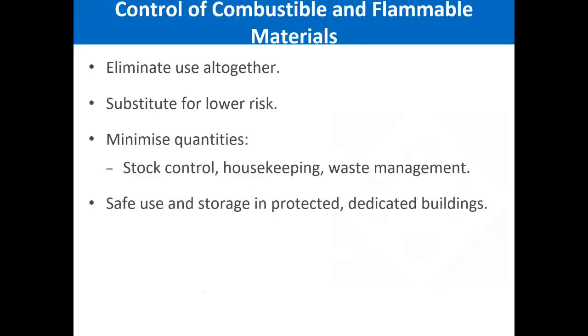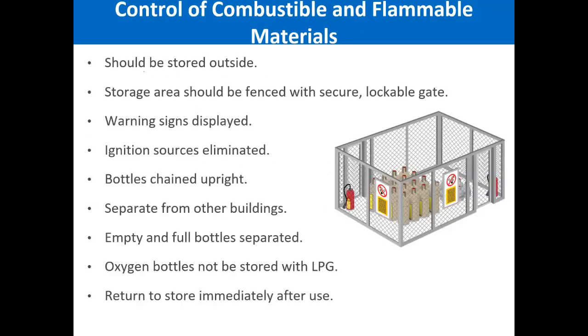Okay, what are the controls for combustible and flammable materials? Obviously, you should try to eliminate the use of combustible and flammable materials altogether. If not, then substitute for something which is lower risk, or which has a lower flammability temperature. Then minimize the quantities. Don't store extra quantities of flammable or combustible material, and make sure there is safe use and storage, and it is in a dedicated building.